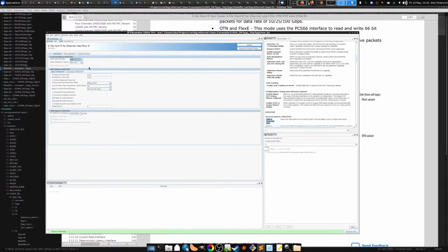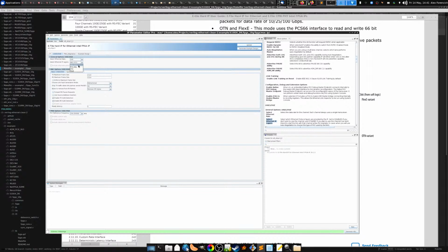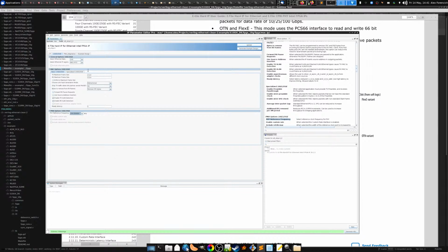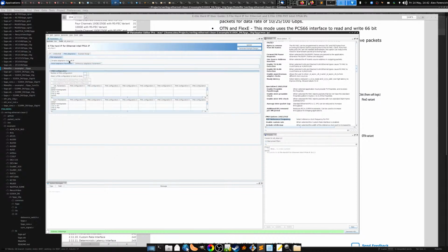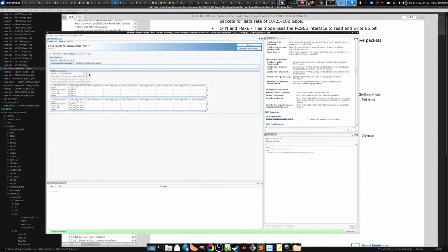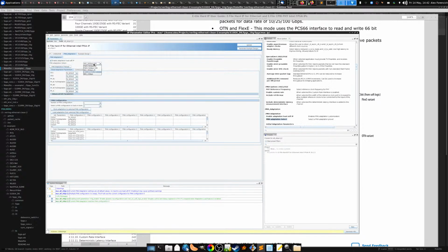All right, so select the rate. We're going to start at 10G. Yeah, so leaving these on means we can go in and poke at stuff from the tools. All right, so MAC and PCS, that's fine. All this is fine, I think. Bidirectional, CRC, okay. And we're going to run this with a 156 megahertz reference clock. All right, so we're going to need the adaptation soft IP, right? We're going to set this to 10G. Yep, okay. Go ahead and store that.